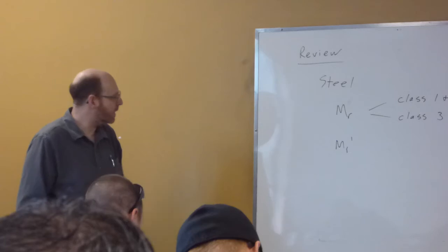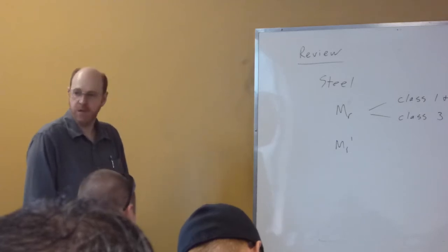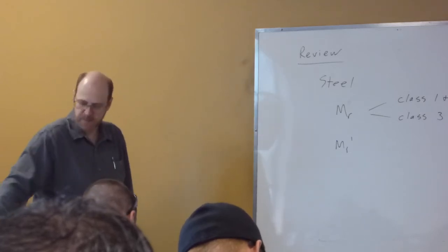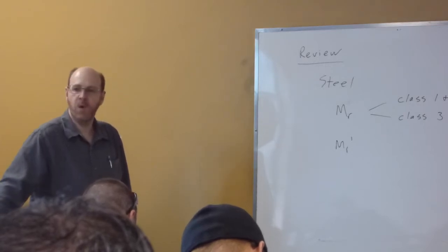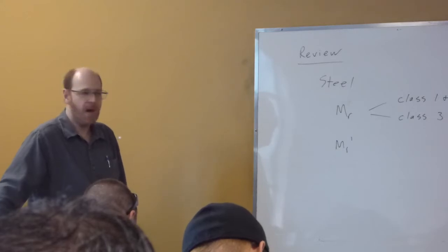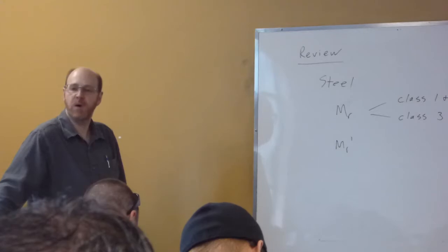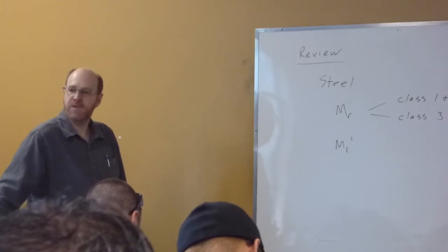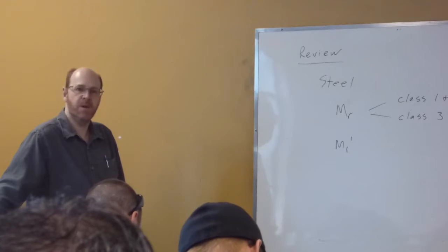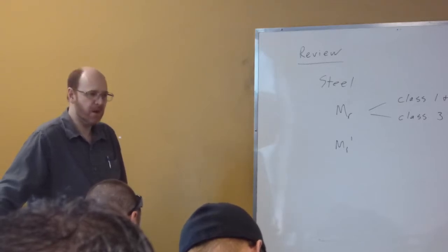So the last thing that we're looking at here for steel is our shear resistance. Now our shear resistance, we're just looking at the web only. So it's area of the web times our allowable stress. And just like with our moment resistance, there's a stress as part of the calculation as well. We're looking at 350 MPa is the Canadian value, but our American steel is 345 MPa.